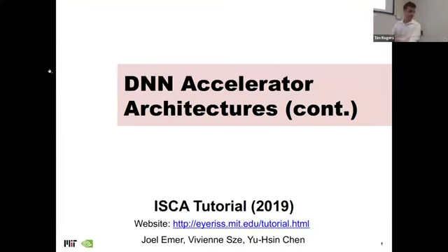All right. So today we're gonna start spinning through a bunch of these other slides on specific DNN accelerators. We finished off last lecture categorizing the sea of early accelerators: basically a bunch of processing elements, at the core of all the operations is a fused multiply-add, and arranging these in a dataflow is much more efficient than the traditional way GPUs do it, moving everything through the register file.